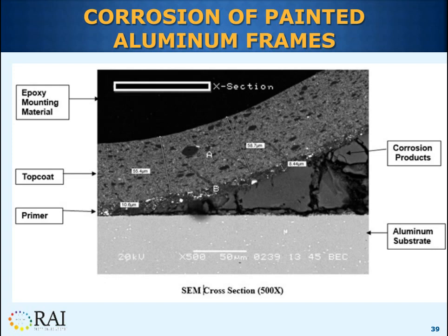If you look at the primer indication and top coat indication on the left of the micrograph, you see that the primer and the top coat lifted off together. And that means that the primer and top coat had good adhesion to each other, so the so-called intercoat adhesion is very good.